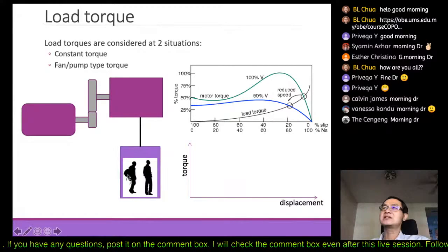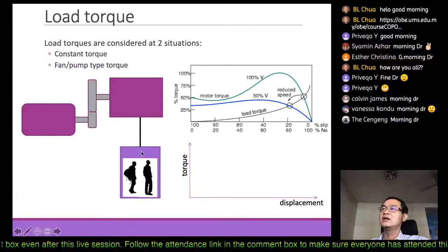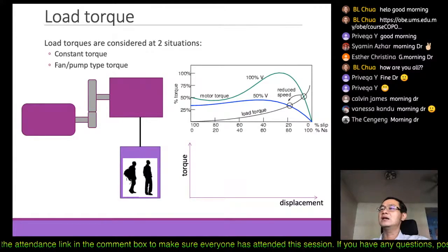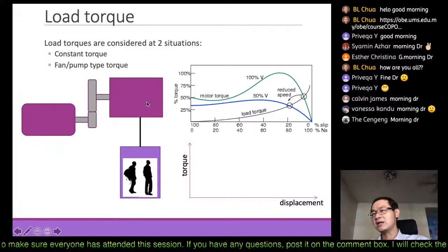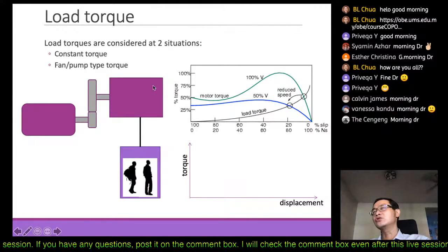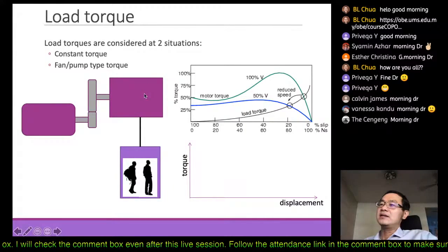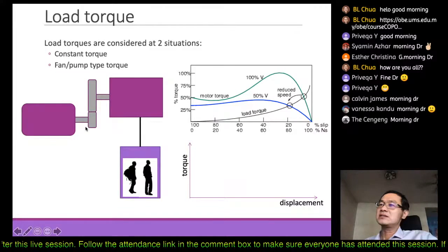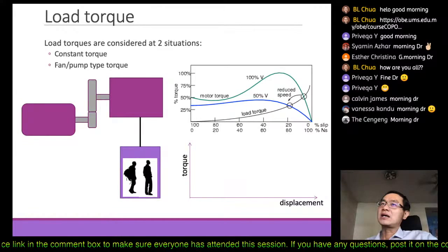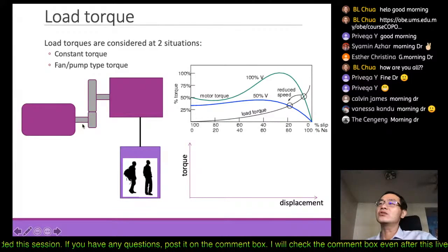We roughly estimate one person is 100 kg, so 10 persons plus the construction of the lift, maybe 200 kg, so 1.2 tons of load. You have to calculate back, 1.2 tons converted to force is 12,000 Newton. Then with a speed reduction of, let's say, 100 times, it becomes 120 Newton, so the load now becomes 120 Newton.